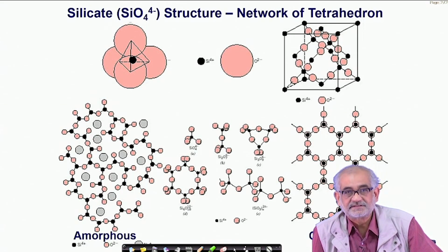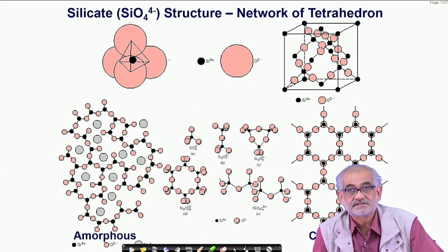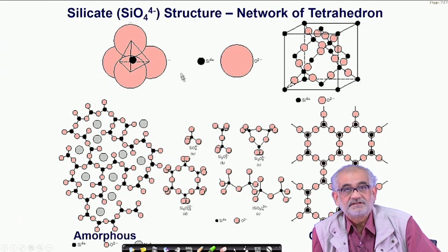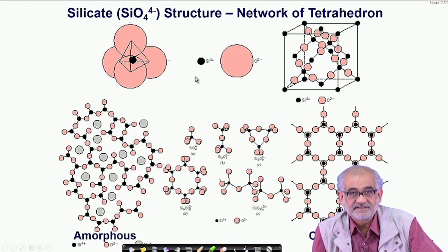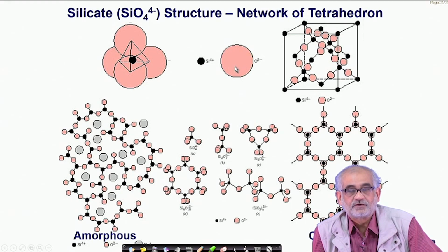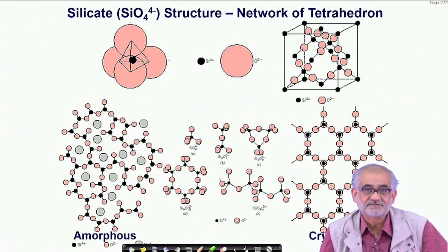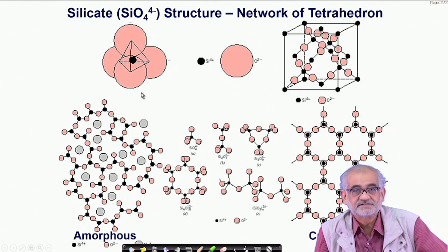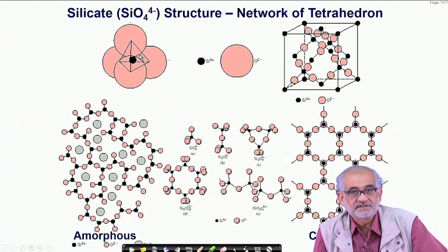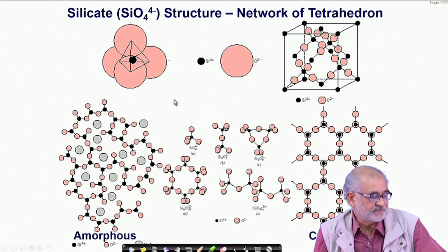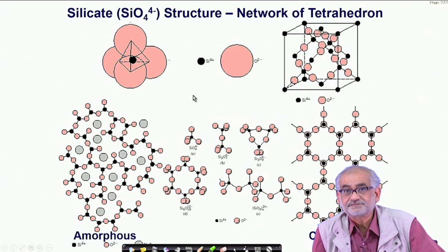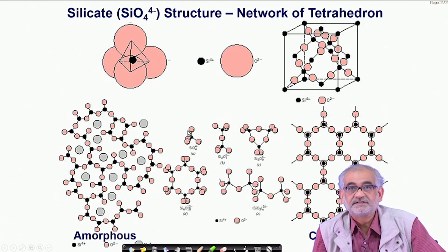And this is dictated by thermodynamic terms. To be more precise, something called the Gibbs energy, which essentially is derived from the intrinsic property of specific heat, showing up in the form of enthalpy and entropy, and the relative contributions of enthalpy and entropy actually decide what is the relative Gibbs energy of a particular phase in a given system. And depending on the relative Gibbs energy, and to be more precise, the chemical potential, one actually decides whether a particular phase is going to be stable or not. And structure does play a role in determining such stability.